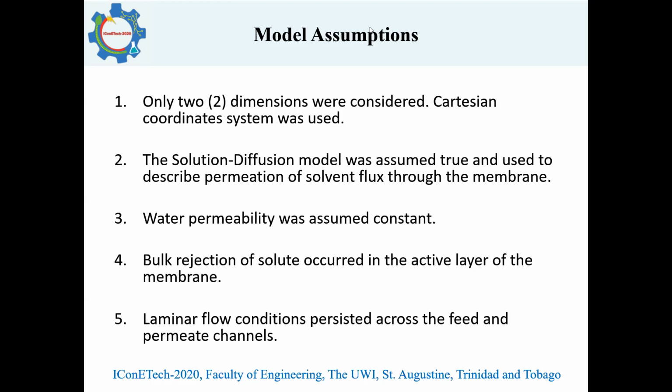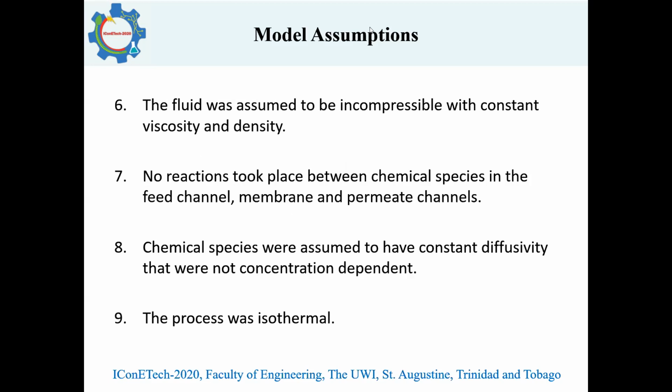Secondly, we assumed that the solution-diffusion model was true, and that is that the membranes that we're looking at are non-porous. We also made various assumptions in terms of water permeability, bulk solute rejection, and laminar flow conditions. We assumed that the fluid flow was incompressible with constant viscosity and density, that there were no reactions between chemical species, constant diffusivity, and that the process was isothermal.